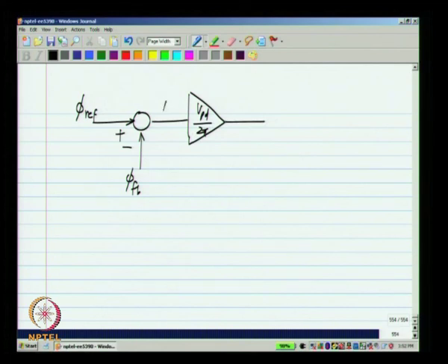Okay. So, the phase difference is delta phi and the average output is VPD by 2 pi. So, there will also be this time varying error that is added to the average output. This time varying error has a peak to peak value of VPD and an average value of 0, and it has this rectangular wave shape.